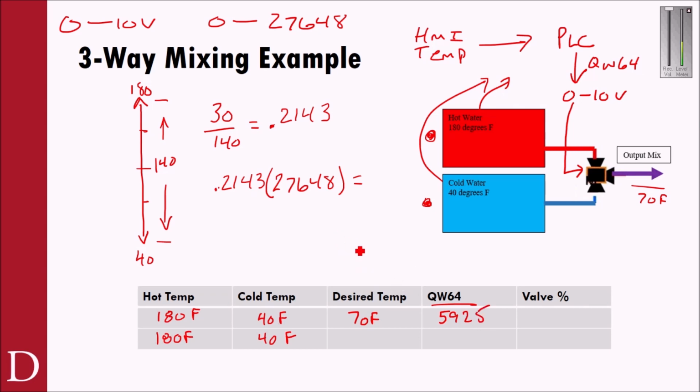Well, what it means is that I'm not at zero, right? At zero, I'd be pumping out 40 degrees water. And halfway at about 14,000, which would be like right here, right? 14,000, if we just kind of ballpark it at this is 28,000 for the analog word, then this would be like 7,000, right? If I wanted exactly 25%.